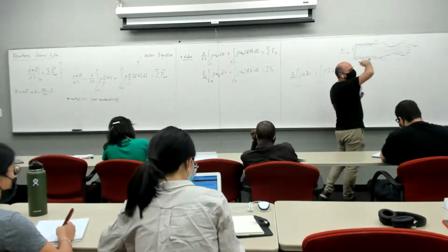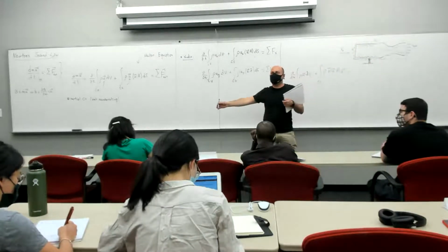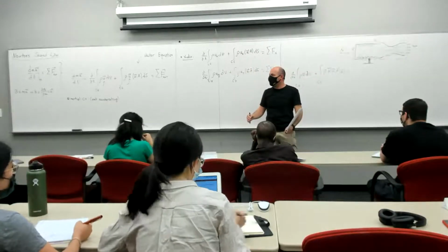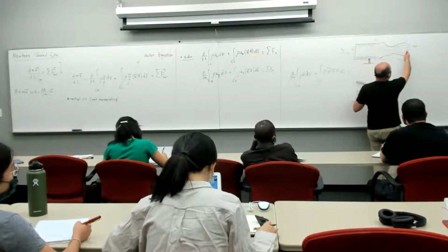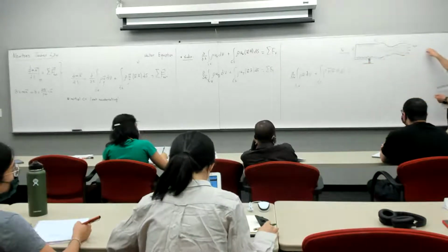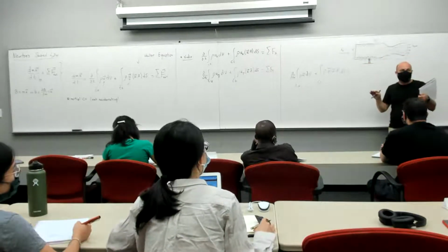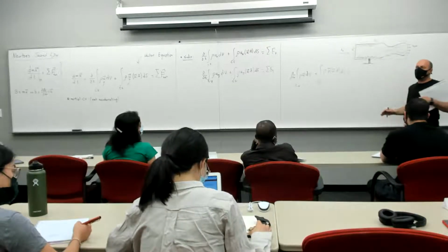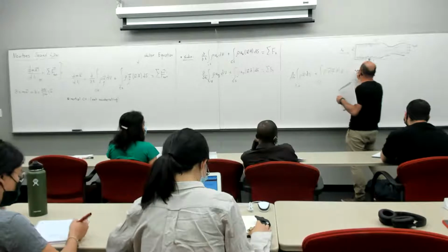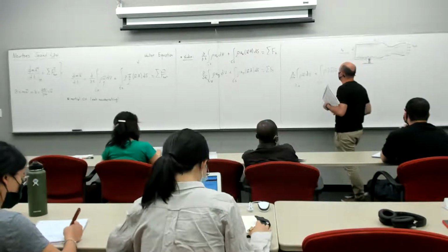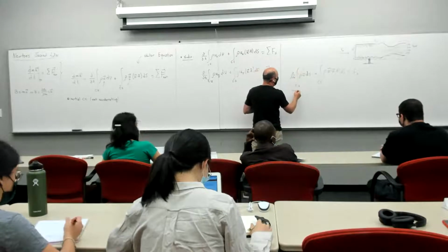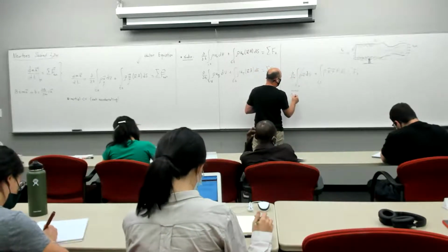We're going to assume there are no other forces because you can neglect the pressure from the atmosphere. You can put this surface far away where the gases have already dissipated somehow, and so you have an equal pressure distribution. So no forces from the pressure. The only force is this thrust force. Okay, you assume steady state, so d by dt is equal to 0.